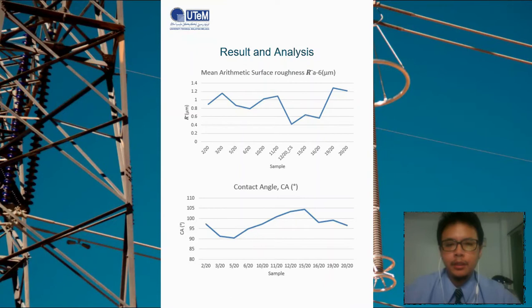Okay, the test sample or degrade sample, which is sample 3, sample 10, 11, 19 and 20 out of 20, on the other hand, showed the rougher surface with measurements ranging from 1.016 micrometer to 1.285 micrometer. The surface roughness values range between 0.568 micrometer and 0.897 micrometer, which is still considered a bit greater than the control samples, according to observation on the sample 2/20, 5/20, 6/20, 15/20 and 16/20.